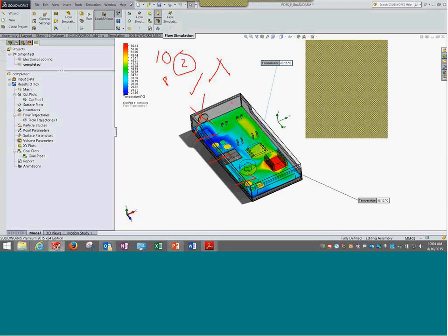Good question. Do the pressure and flow rate at the fan inlet give implications on the stall region? Yeah. The fan curve is a property of a fan, and it is nowhere related to the system. So the stall region for a fan can be derived irrespective of the system. The pressure difference coming from this system is a completely different topic. But if you're talking about the fan curve, yes, it does imply the stall region, or it can help us understand the stall region.